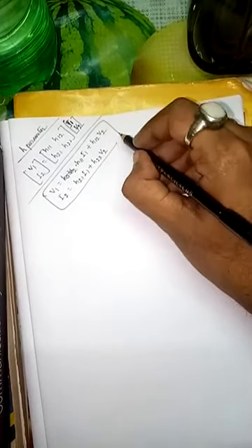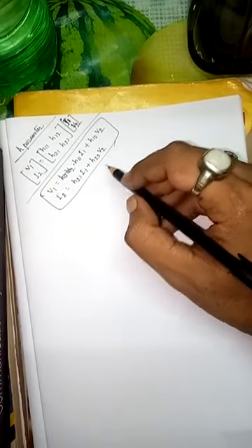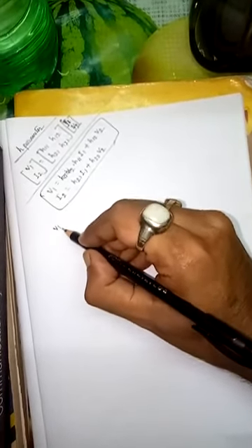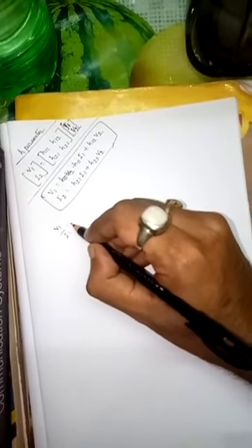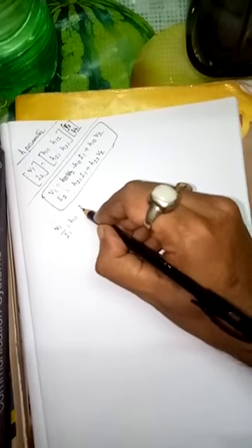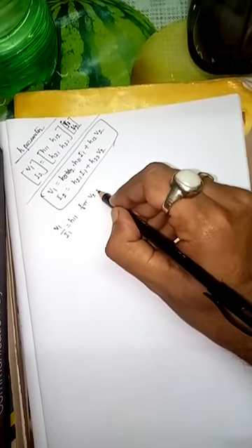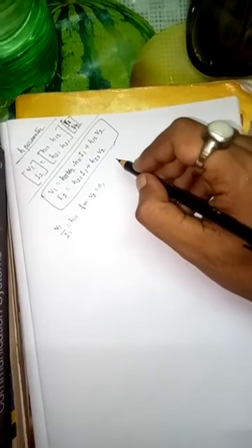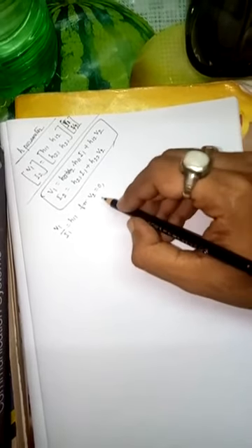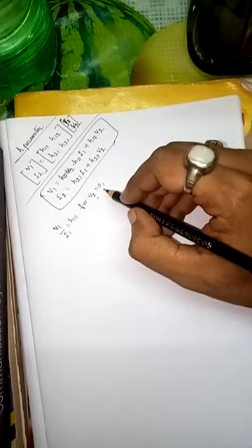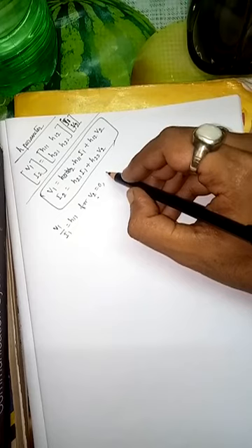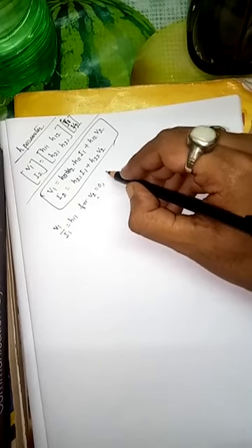Now how we can relate Z parameter using this? Here if you are writing this H parametric form, V1 by I1 equals H11 for V2 equals 0. Now that V2 equals 0 condition directly follows the Y parameter. So what is the Y matrix?